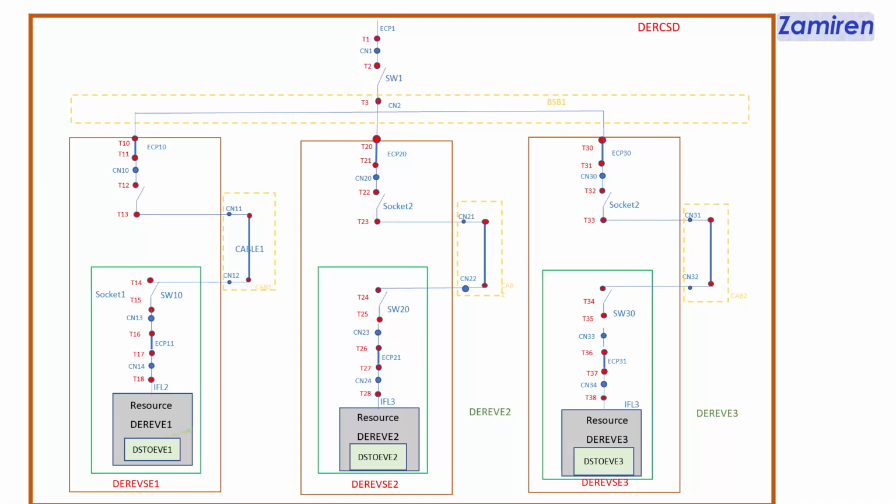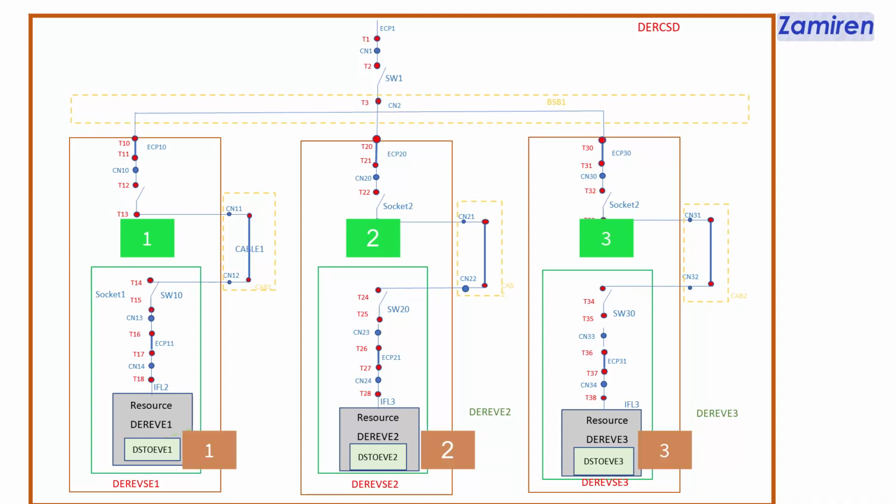The single-line diagram of the model is as follows. The DER resource constituted by the station is connected to the upstream network at the ECP1 point. It includes the 3 DERs that are EVSEs, which themselves include the 3 DERs that are constituted by vehicles when they are connected.